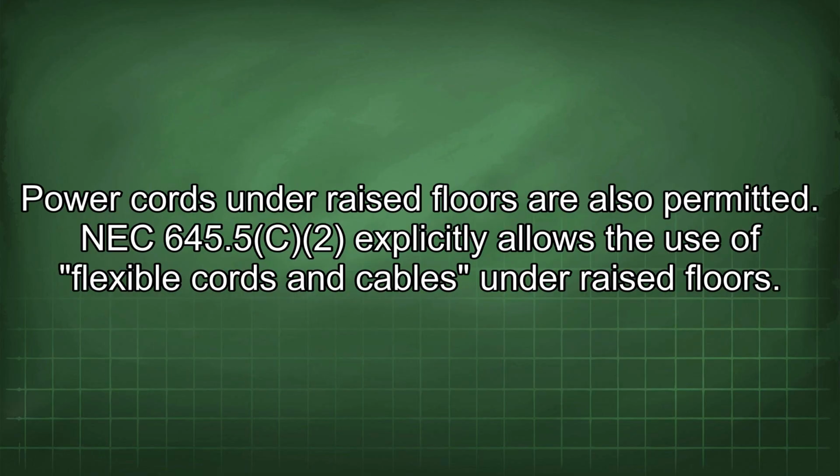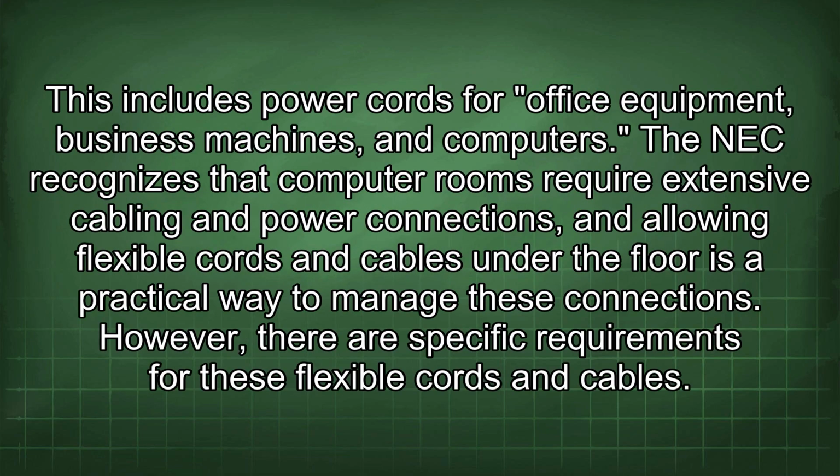Power cords under raised floors are also permitted. NEC 645.5 C2 explicitly allows the use of flexible cords and cables under raised floors. This includes power cords for office equipment, business machines, and computers. The NEC recognizes that computer rooms require extensive cabling and power connections, and allowing flexible cords and cables under the floor is a practical way to manage these connections.